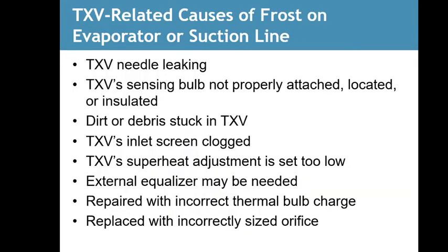TXV related causes of frost on evaporator or suction line: TXV needle leaking, a sensing bulb not properly attached, located, or insulated, debris or dirt stuck in a TXV, inlet screen clogged, superheat adjustment too low, external equalizer may be added, repaired with incorrect thermal bulb charge, replace with correct size orifice.